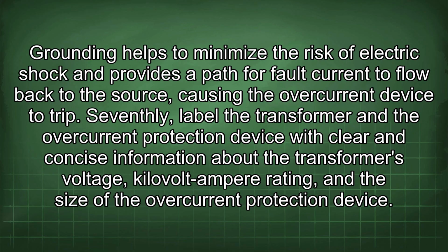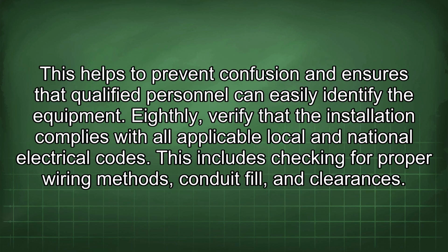Seventhly, label the transformer and the overcurrent protection device with clear and concise information about the transformer's voltage, kilovolt-ampere rating, and the size of the overcurrent protection device. This helps to prevent confusion and ensures that qualified personnel can easily identify the equipment.